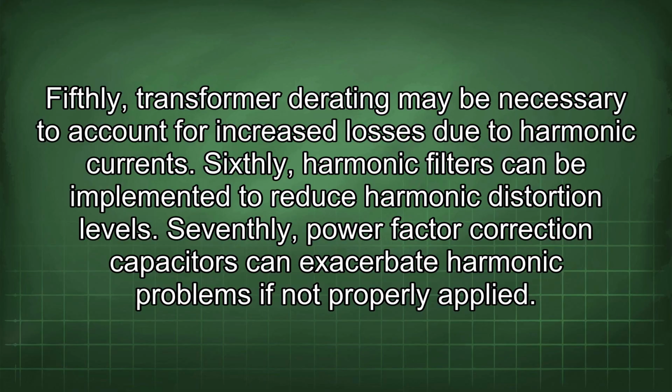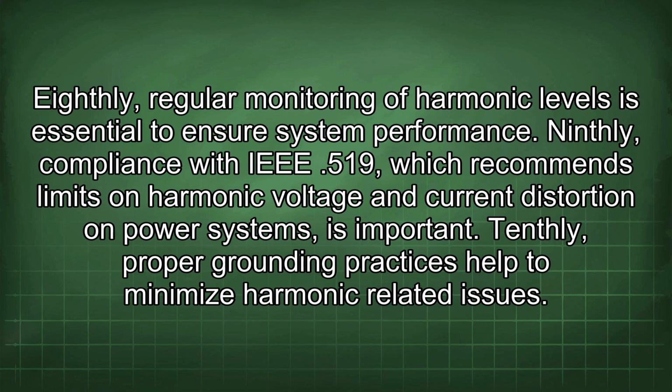Seventhly, power factor correction capacitors can exacerbate harmonic problems if not properly applied. Eighthly, regular monitoring of harmonic levels is essential to ensure system performance. Ninthly, compliance with IEEE 519, which recommends limits on harmonic voltage and current distortion on power systems, is important. Tenthly, proper grounding practices help to minimize harmonic-related issues.